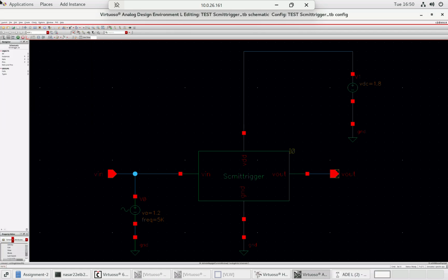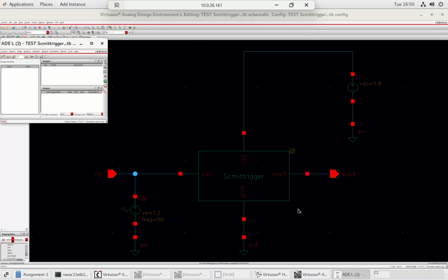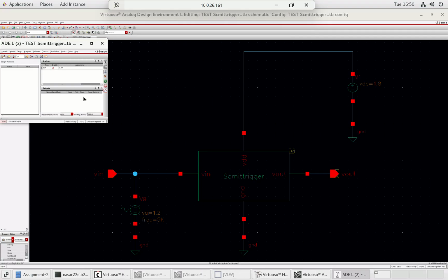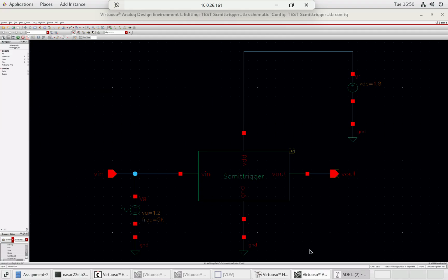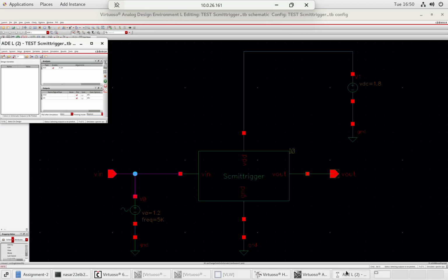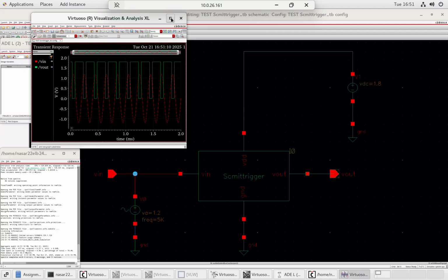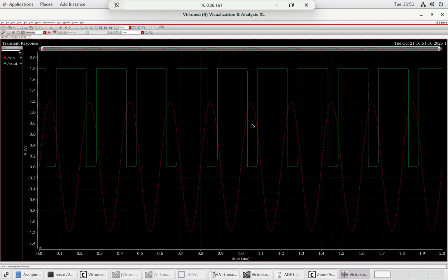It will take time. Okay, so transient analysis, stop time is the same which I have done earlier. Click OK, and outputs to be plotted. Select on design, the one out here, and the input is here. You can see here the input and output have been saved. Now click on OK, run button. Here the input and output have been shown as we have already done it.